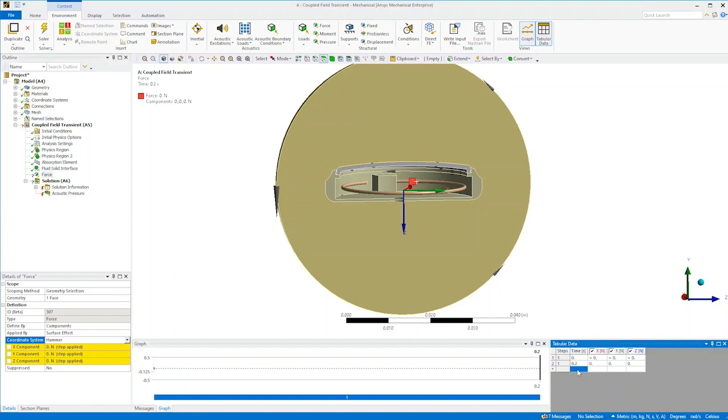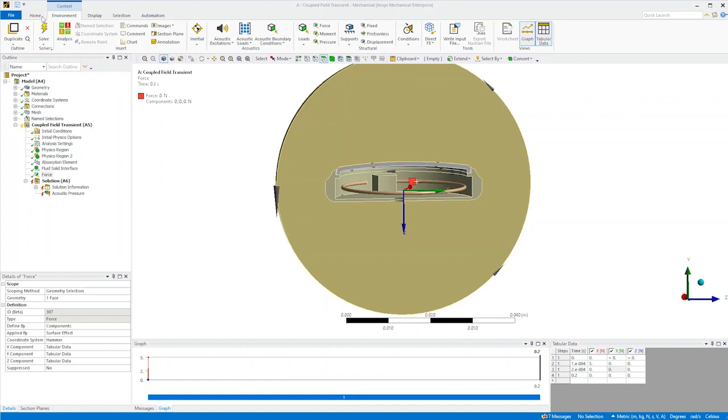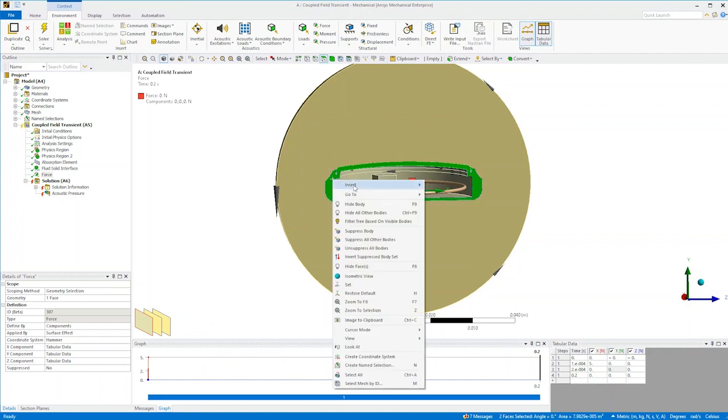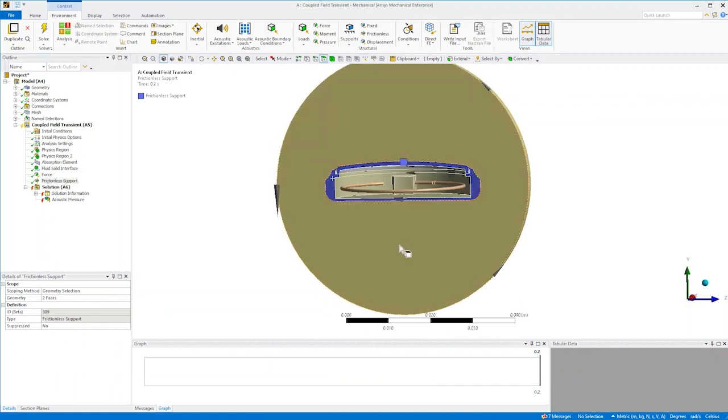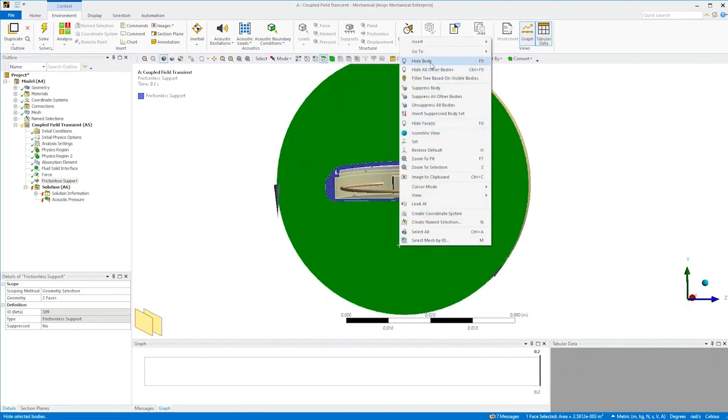Note that the hammer could also be added in this model, and its impact simulated by switching on non-linearities. Further structural boundary conditions are added. Remember that we model half the case and a full gong to save time.